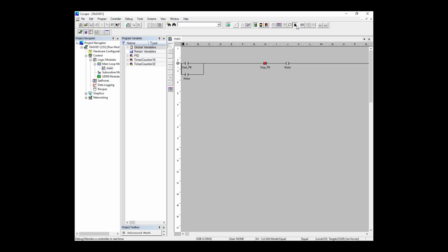As you can see, we have the availability of power flow on the stop push button, but none anywhere else. If we go to our start push button, it is controlled by the touch screen. So I'm going to go ahead and touch it. And you'll probably hear a beep. And now I've released the push button, and as you can see, the debugging works very well. Okay, that's just simple Boolean logic, creating variables as you program.